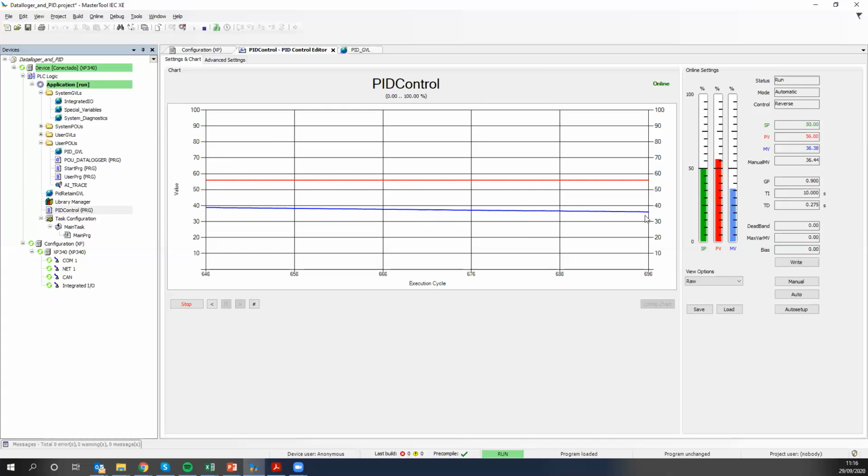This decreasing is given to us by the integral time, the time integral here. So I will change the signal from the error. I will send in the PV less than the SP. Again, the integral time is trying to react to this. If I want 50 degrees, for example, and my process variable is giving me information that it's 40, of course, it will increase my output, open my valve to heat my system.